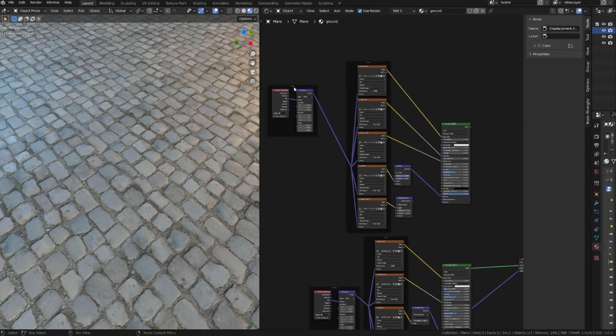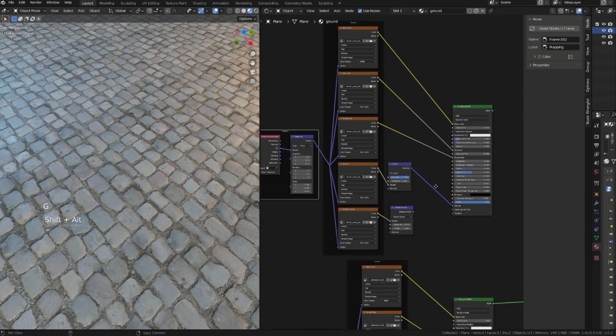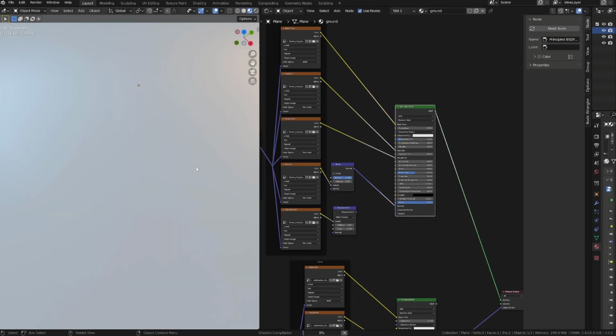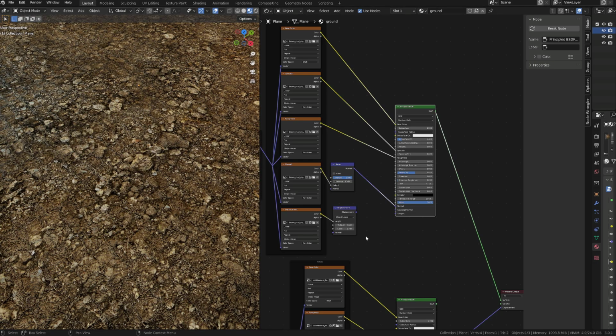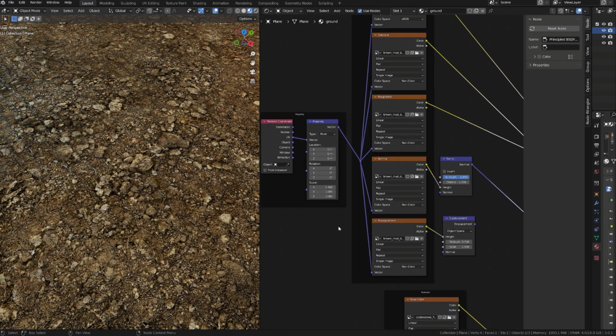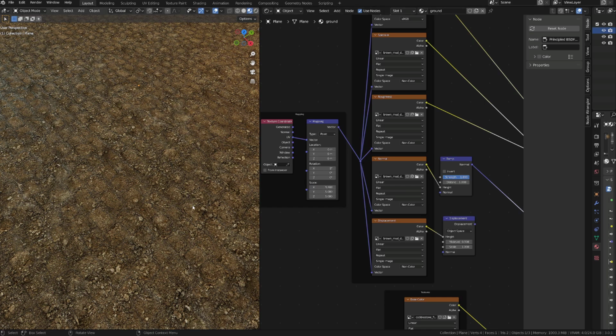To be able to preview this new texture set, I will Ctrl-Shift-left click the Principled BSDF node. You can use this shortcut on any nodes to preview the result. Blender will automatically set a viewer node, that is a simple emission shader, or if you do it directly onto a shader node, it will plug the shader node directly in the shader output. We can now preview our mud texture. I will set its scale to 5 so that it fits the other texture.